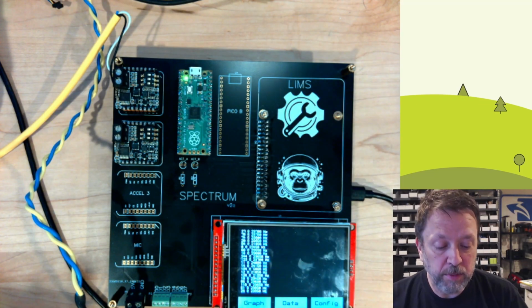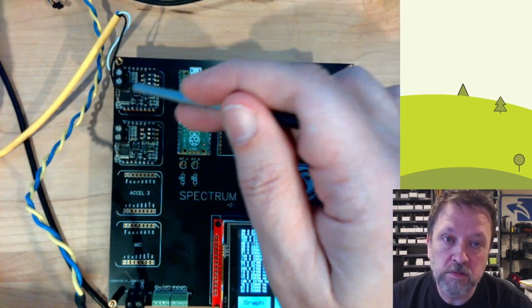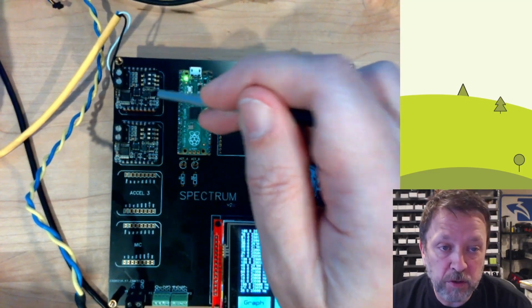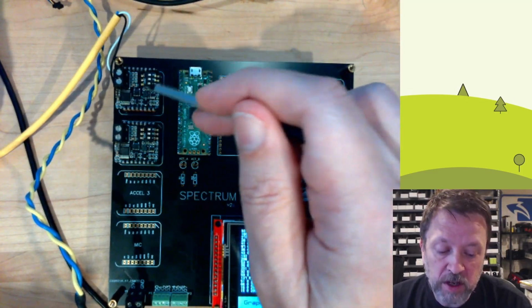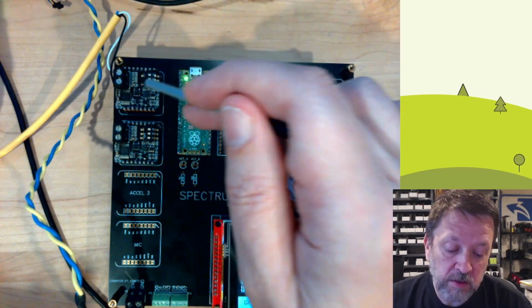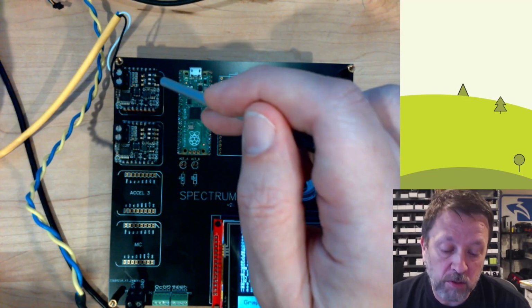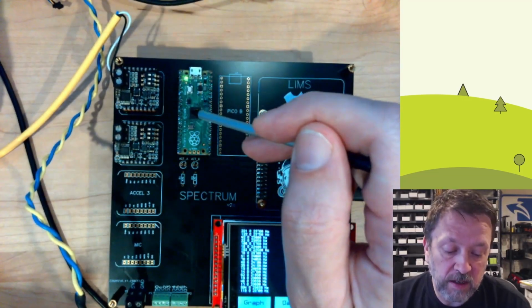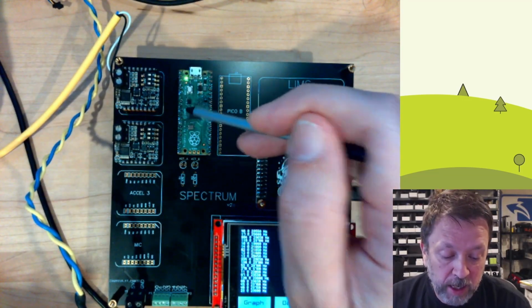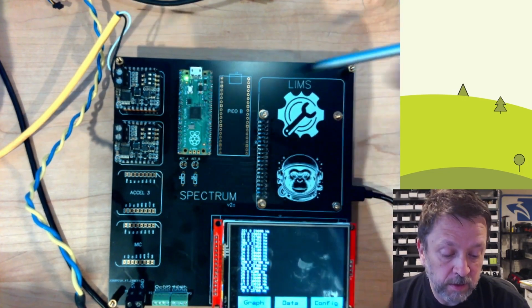So really what happens here is this signal comes in to this 4 to 20 filtered I/O piece, and I'll talk more about it in a minute. But basically, this takes that 4 to 20 and turns it into a 0 to 3.3 volt signal. That comes over into this Raspberry Pi Pico into one of its A to D channels.